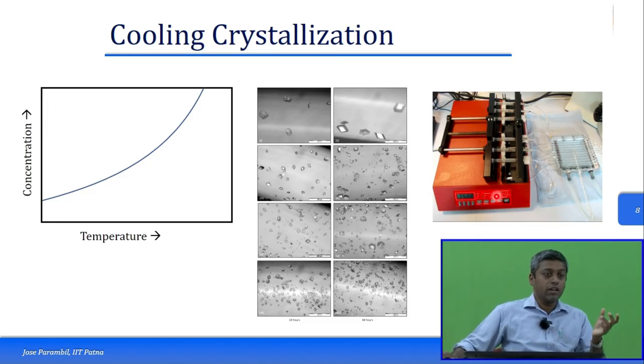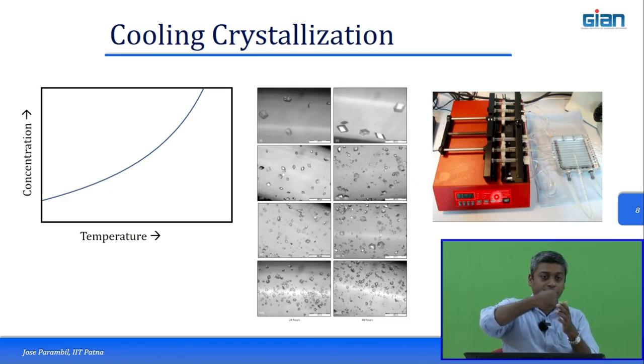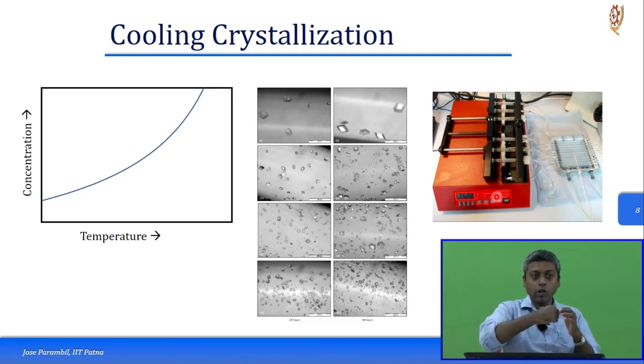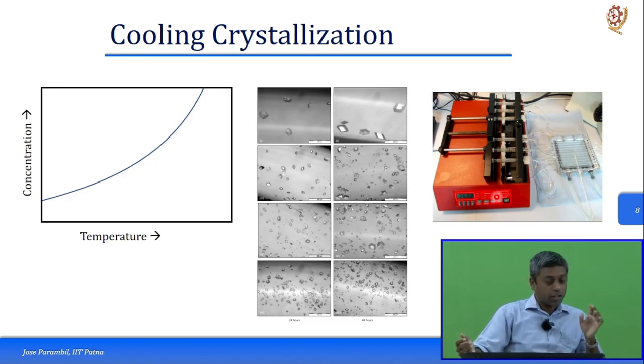For example, instead of a syringe pump like this, we have tried putting in a peristaltic pump for continuous operation. But what we found is that in the peristaltic pump, as the pump grinds through the tubing, it makes a pressure wave and pushes the liquid forward. During that phase, there is a small region where it is squeezing the flexible tubing and pushing it forward, where the shear increases tremendously. The proteins start to denature at that particular point.